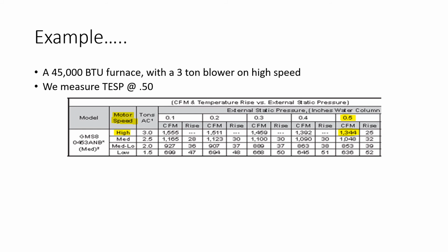And that's really what we're looking for: what is the force that is acting against that blower wheel? So we just disregard the positive and negative values, and we add the measurements together. For example, I think we had a 0.3 and a 0.2, so we would add them together to 0.5. It wouldn't end up being a 0.1 where they cancel each other out, because both of those forces are still acting against the blower wheel.